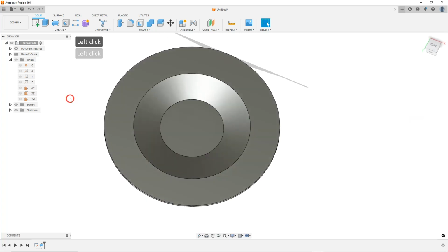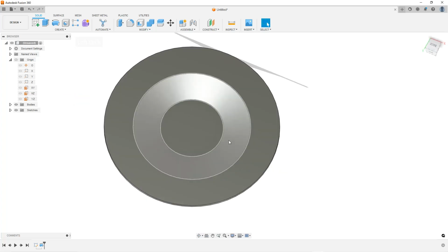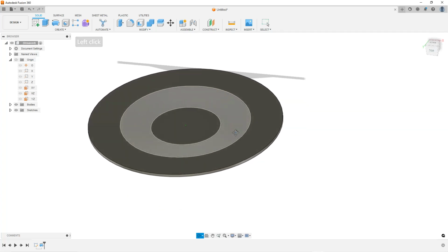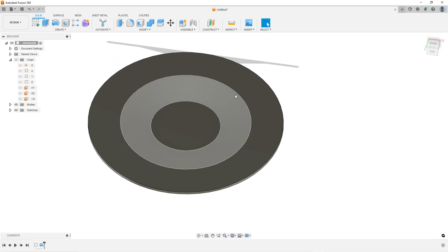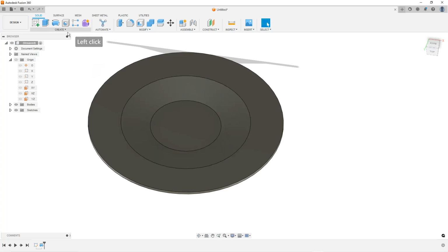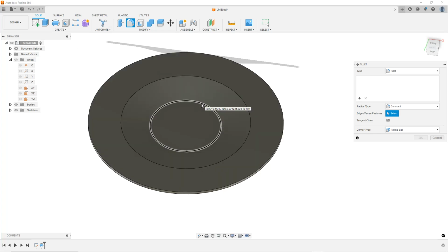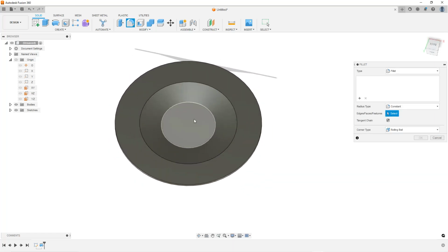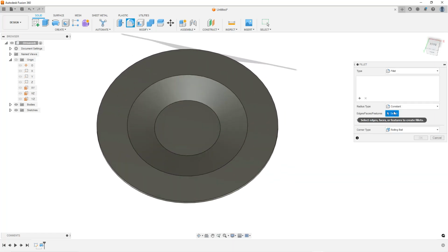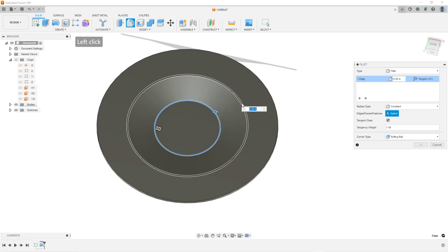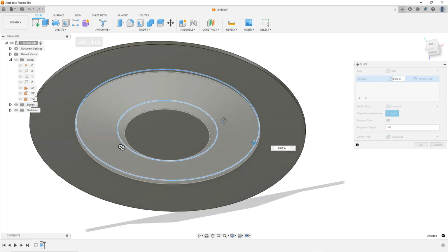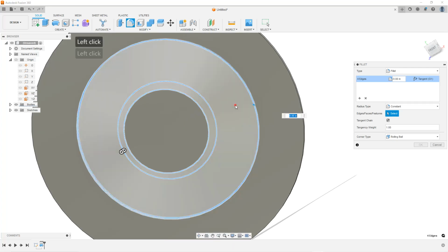And now the next part of the operation, we're going to start cutting pieces of this out. Before I do that, I want to add some fillets to make this a little smoother. And typically I'm not going to add fillets unless it's something I would do in terms of manufacturing, because my main line is really being a machinist. And I see a lot of drawings where people just fillet everything, and it's completely unnecessary and unrealistic, and it adds a lot of cost to the designs that you really don't need.